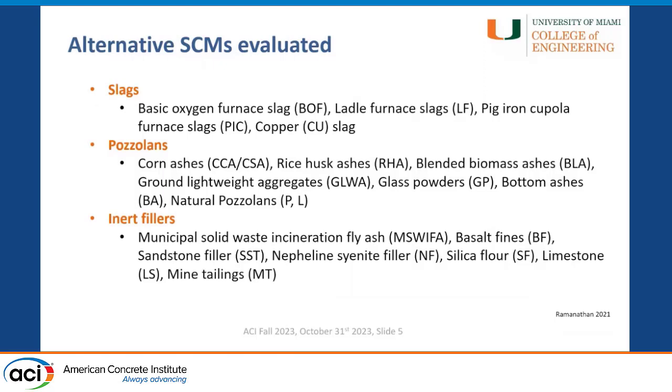So in this particular work, as my title says, I evaluated a number of alternative SCMs. The motivation for this is that our fly ash supplies are dwindling, your thermal power plants are getting shut down. You have a lot of clays, which is one source, which is an alternative SCM source. You have other sources of SCM, such as steel slags, etc. So we wanted to systematically see what all these alternative sources of SCMs can do.